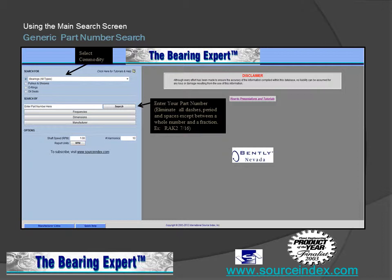The generic part number search is the most popular way to locate bearings data in the toolkit. When entering your part number, eliminate all dashes, periods, and spaces, except in between a whole number and a fraction. For example, RAK2 space 7/16. If you are going to search for a bearing by dimension or manufacturer, you must go up to the search criteria box and select a bearing type from the drop-down menu above.